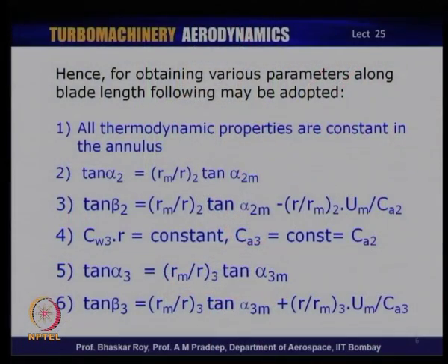And the free vortex design, as I just mentioned, has been used pretty widely earlier, but it is not widely used in many of the modern designs anymore. So, if you get free vortex design, this is what you would normally get, very similar to what we have received in axial flow compressors.